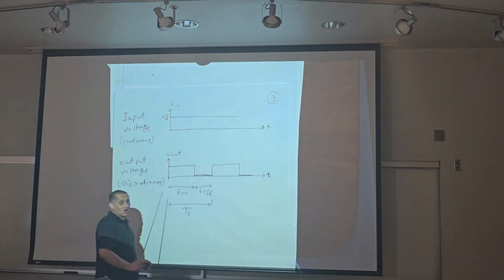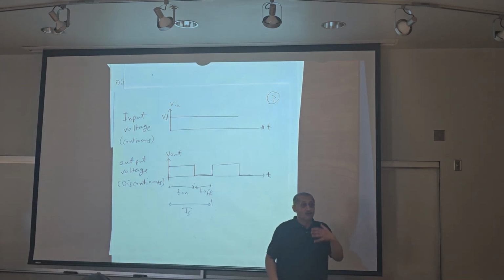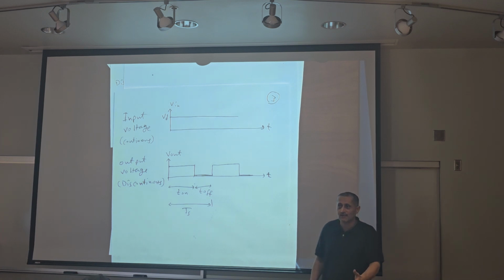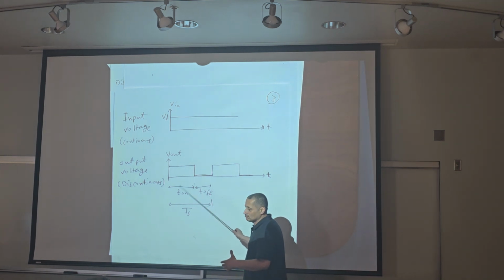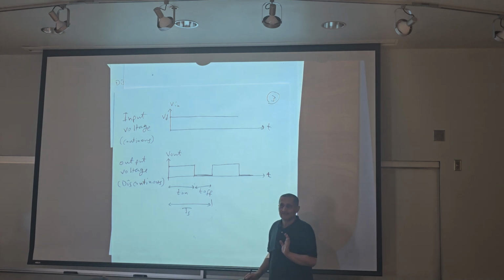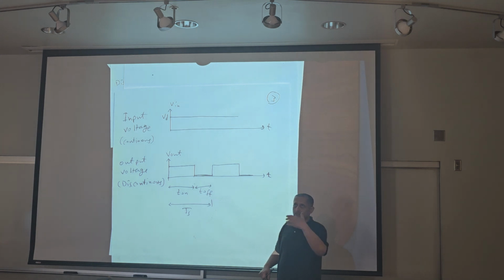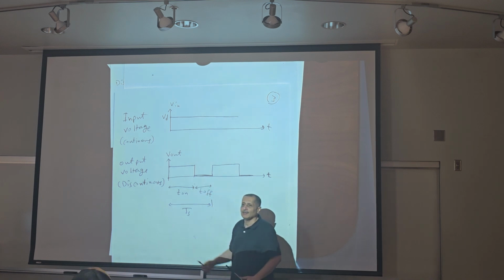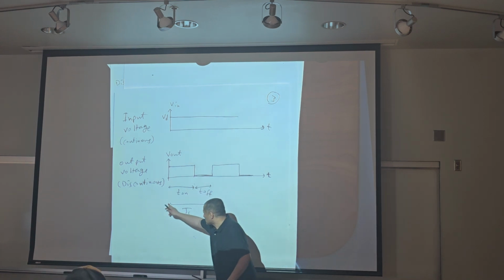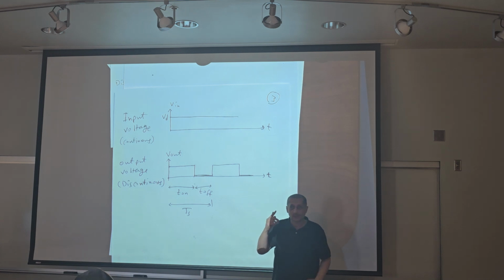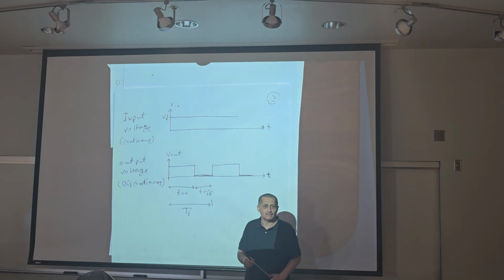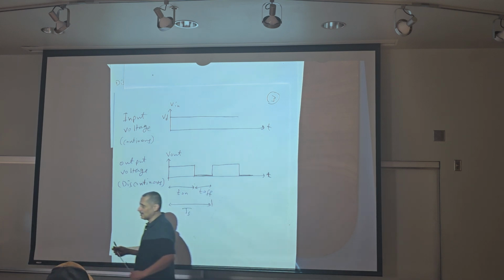This is the on time. On time means the transistor or the switch, thyristor, any device used, is on. T off is the time when the device, thyristor, MOSFET, field effect transistor, or BJT, is off. TS is one period and includes the on time and off time.